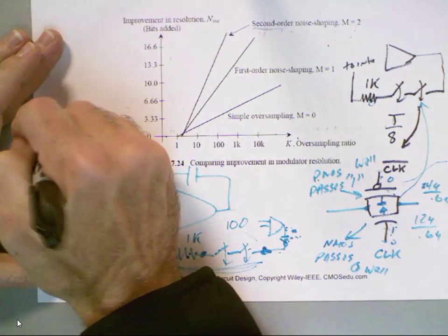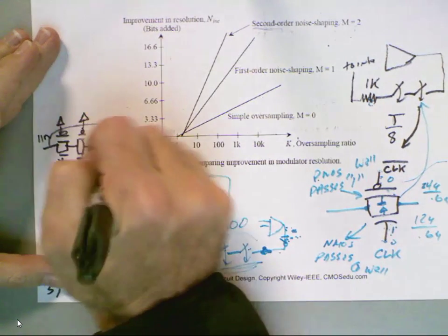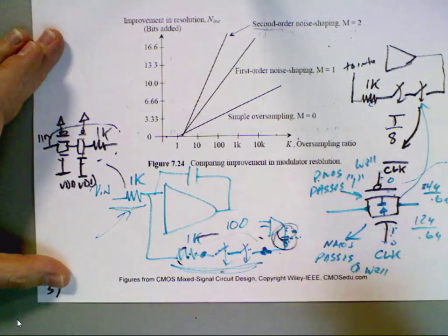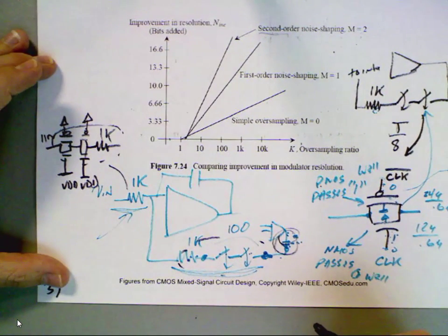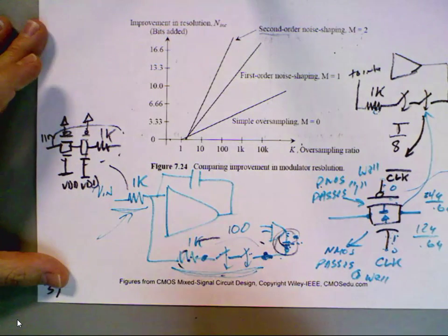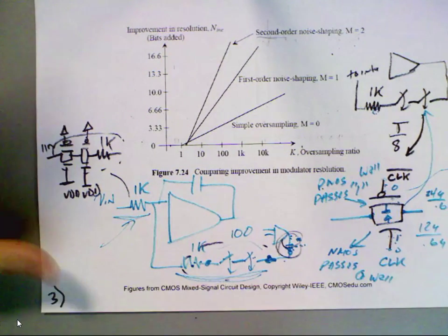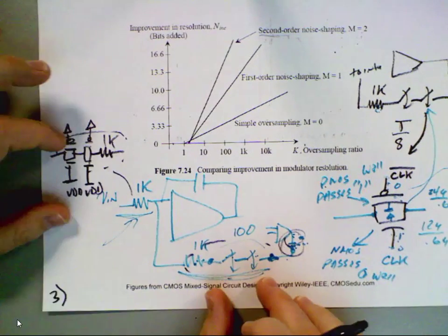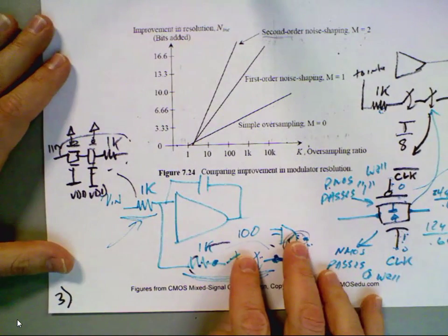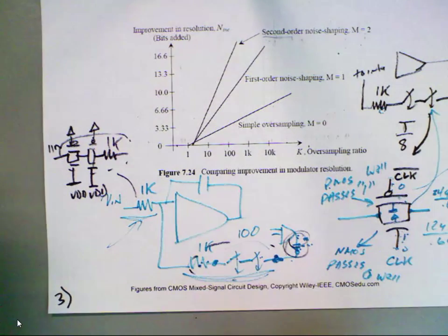And then there's my input. And now this resistance will track this resistance minus whatever the drive is of your output comparator. Does everybody see the issue? Okay, so let me just comment on this a little bit further. Does everybody understand? Okay, so if you don't do this, you're going to get a gain error. Okay, so just be aware of that.